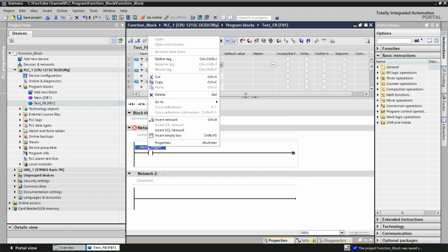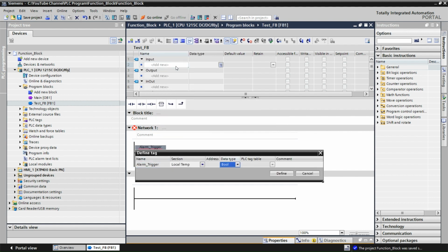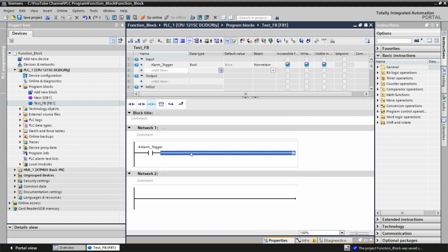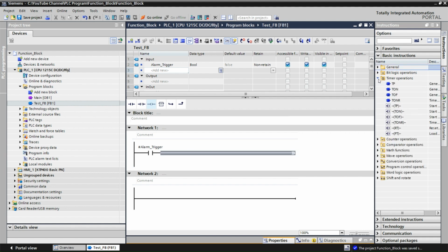So you click it, and then you can use the trigger signal as a local input. Once you receive the alarm signal, there could be a false alarm, or maybe an alarm fluctuation because of the temperature reading going up and down. You need to give a delay time to achieve this, and then you can trigger the alarm. So we need to use the timer.